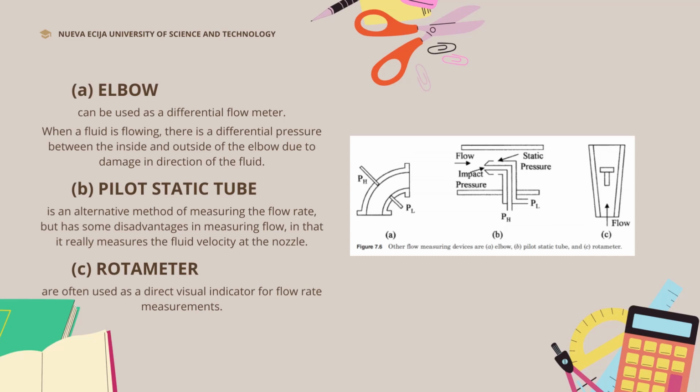The velocity of a fluid or gas flowing decreases as it goes higher up the tube due to the increase in the bore of the tube. Hence, the buoyancy and the weight reduces the higher up the tube it goes. An equilibrium point is eventually reached where the force on the weight due to the flowing fluid is equal to that of the weight. The higher the flow rate, the higher the weight goes up the tube. The position of the weight is also dependent on its size and density, the viscosity and density of the fluid, and the bore and taper of the tube.